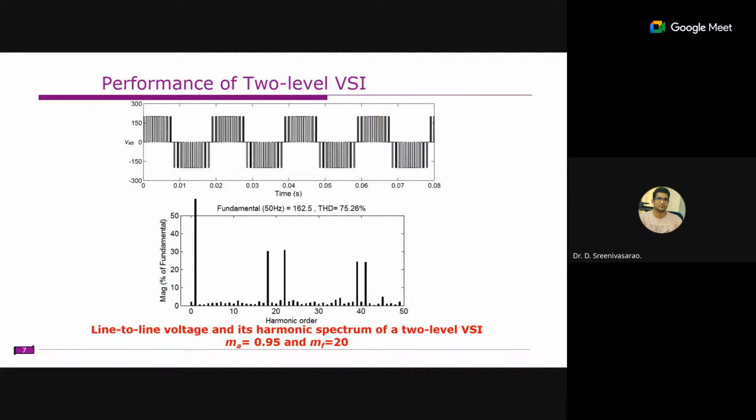Most of the time, to control these inverters, there are two PWM control methods: the current control method and the voltage control method. In the voltage control method, you require a modulating signal and some carriers. By comparing the carrier and the modulating signals, the switching or firing signals are generated for each phase, and the inverter operates as a controlled voltage source.